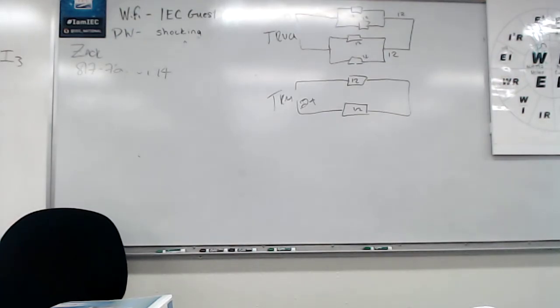So, we leave the truck on one side, and we hit a positive, a negative. Then we jump over to another negative. Is that parallel? That is parallel. So there'll be two batteries connected in parallel. That's 12. Yes, that's 12. Okay. Then we leave the negative and go to a positive. No, we need a positive. We're going exactly the way it looks. Leave the positive and go into a negative. So it's 24. And that'll be this guy.